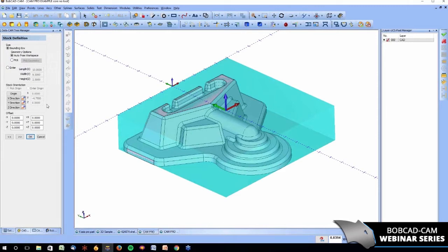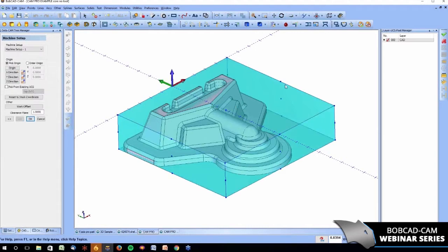Now, you guys can then go in and make the adjustments as needed to the actual size of your stock. And then when you hit next, the most important part is picking your XYZ 0. Now, the nice part with this is you can pick origin. You can pick anywhere down here. You can pick anywhere on the model, and you guys can go ahead and actually set up the direction of your cut. X is one way, Y is another, Z is vertical, those type of options.